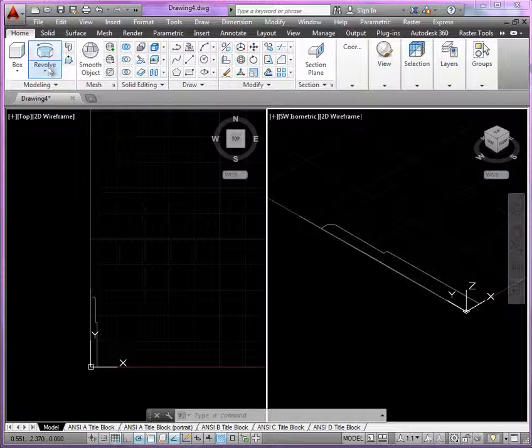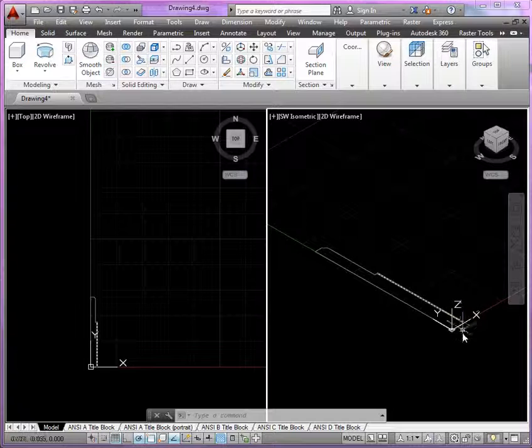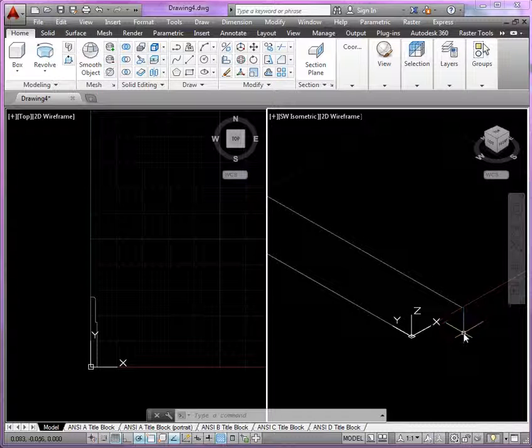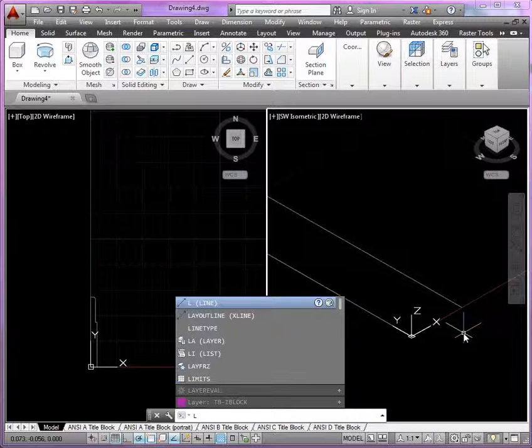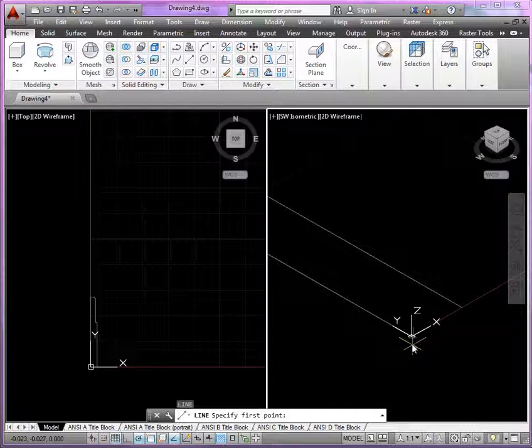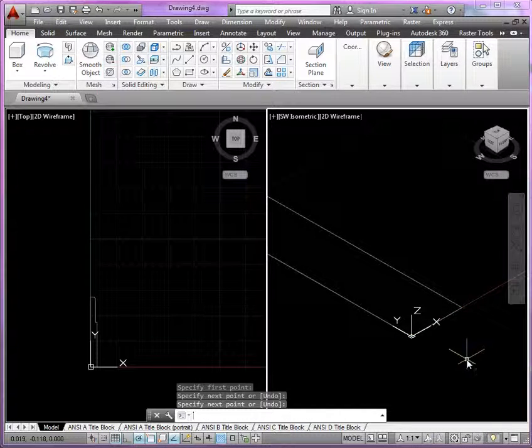So using the revolve command, we're going to select the region profile right here. Right now, as I was trying to revolve it, I actually noticed I don't have a region there, and that's because the bottom part right here was left open. So this is the other edge that we want to close, from this line to here.